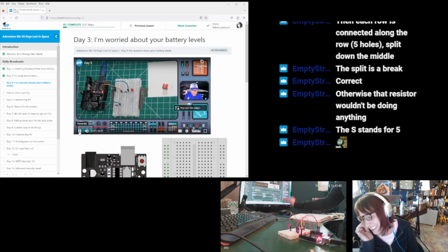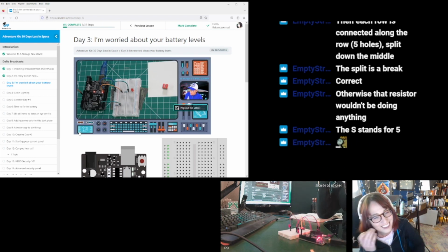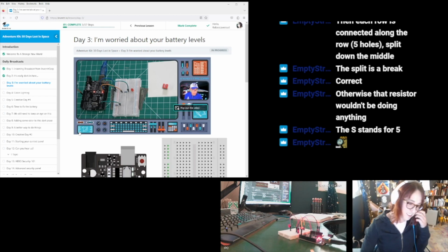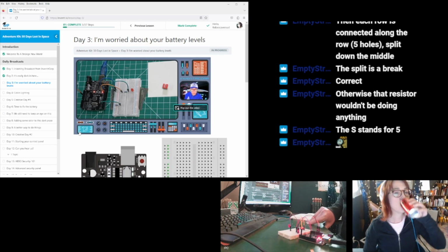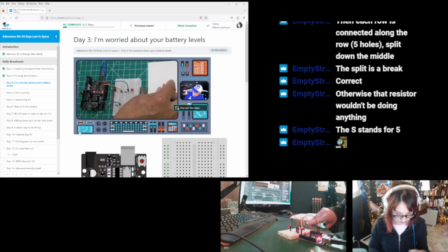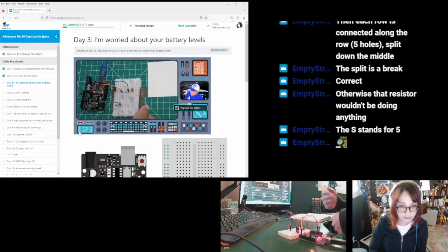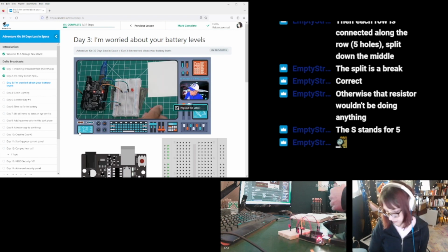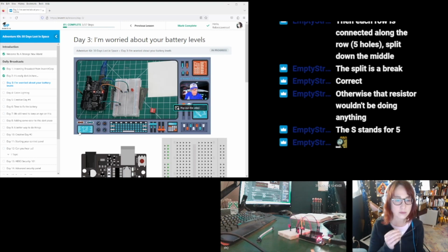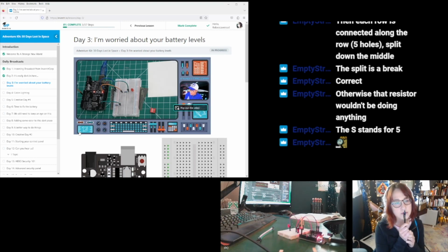Today's exercise is to figure out a way of turning the light on and off without having to re-upload the program to the Hero every time. And we're going to do that using this dip switch. Now, you might think that all we want to do is just take the switch and put it in series with the circuit that's carrying current through the lamp.